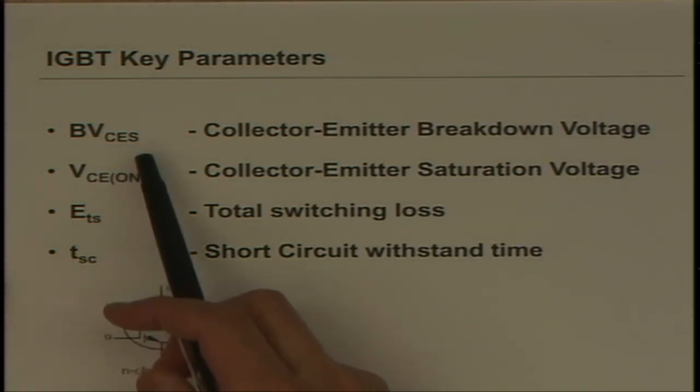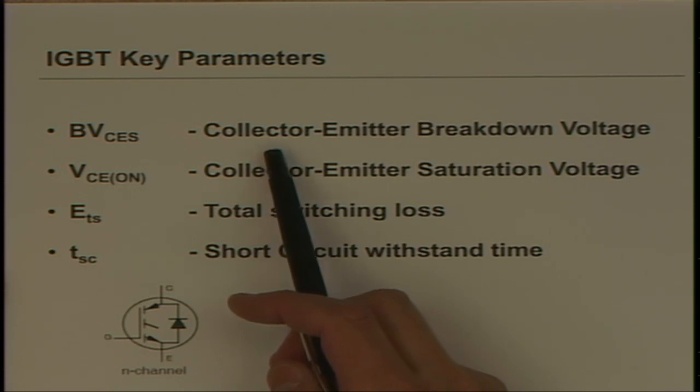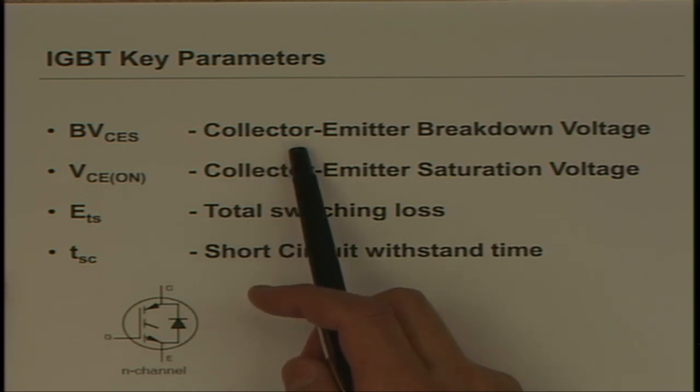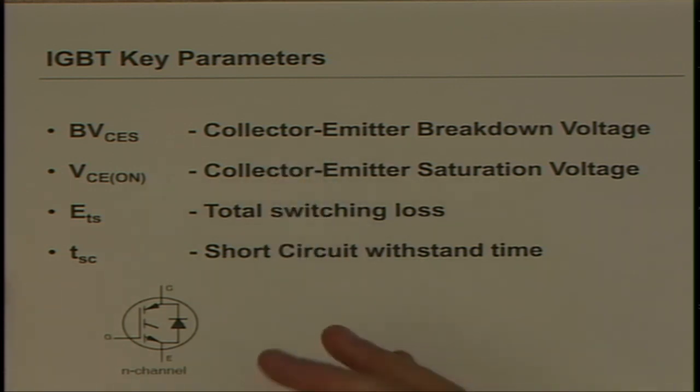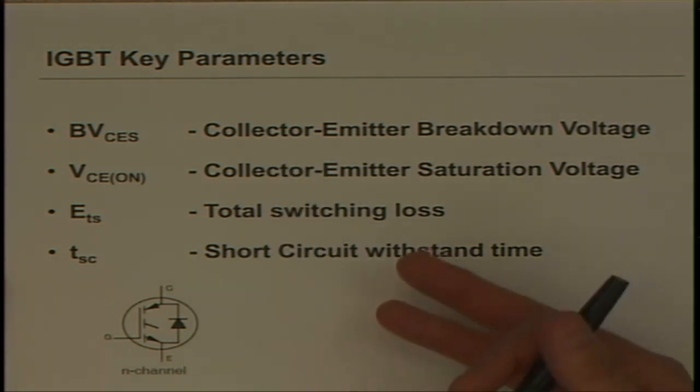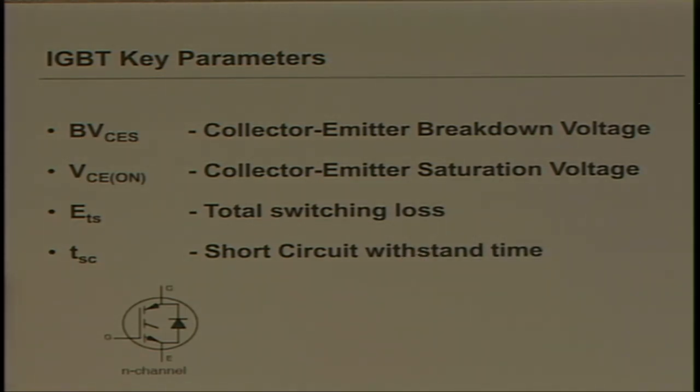This is collector emitter, and these are typically bus voltages, commonly either 3 to 400 volt, which is the rectified line. So a universal power factor corrected line is in that range, usually 380 to 400 volts. At higher voltage, when you rectify 480 volt three-phase, you have a 7 to 800 volt bus. So the devices are rated at 600 and 1200 typically.